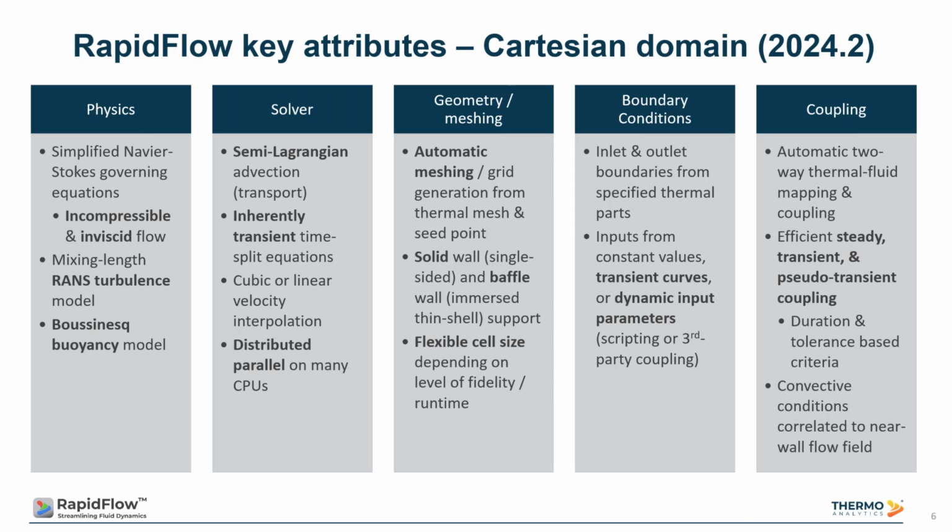You just have to march forward far enough for the flow field to be properly converged, and we can still sync up the coupling properly. And then in terms of the convective conditions that are the kind of key thing being mapped from the fluid domain, the way those are correlated to the near wall flow field also has flexibility that the user can customize.